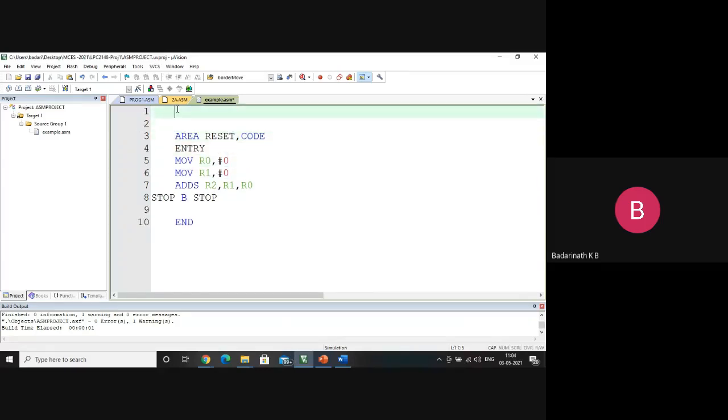Look at this for a moment. Now, my number: D31 is the last bit. Then after that, D30. Then it is D29. Like that, it continues. Then it comes to D1. Then the next is D0. So how many bits are there in my number? Totally a 32-bit number. 32 bits are there. In these 32 bits, D31 is the last bit. We call it the MSB bit. D31 is called the most significant bit.